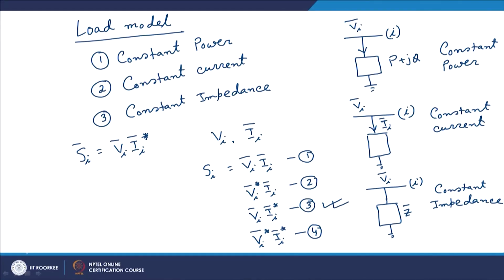Now, this is basically due to the convention we take. This per se does not have anything to do with any technical reason, but it is actually due to some convention. Now, what is meant by that? By convention in power system analysis, we consider the power drawn by an inductive load to be positive. So, what does it mean?